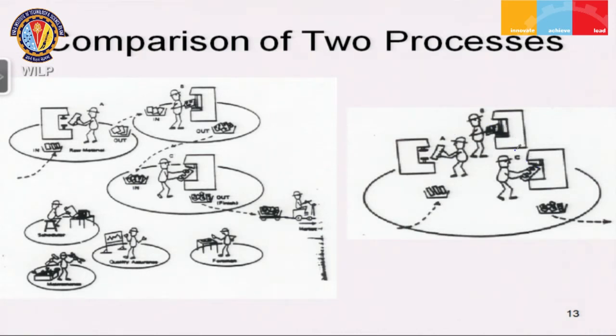Now you see, number one, that there is no batching of the materials between operations, so that time is collapsed. Secondly, what you see is that there is no delay associated with the time required for moving the part between operations that we had in the previous case, because here each part is being directly handed over from one operator to the next. Also, because all three operators are in one area, actually supervision becomes a lot easier.